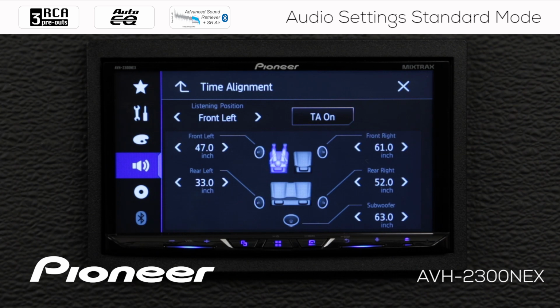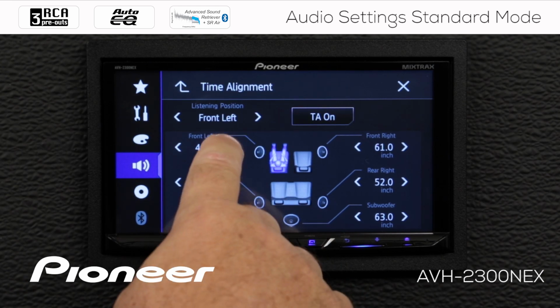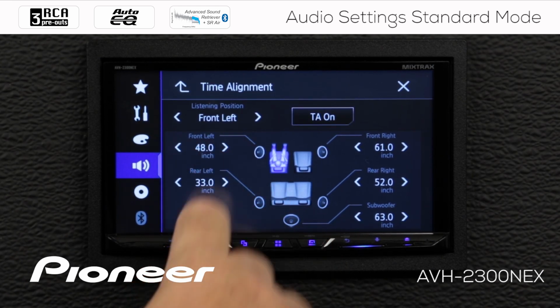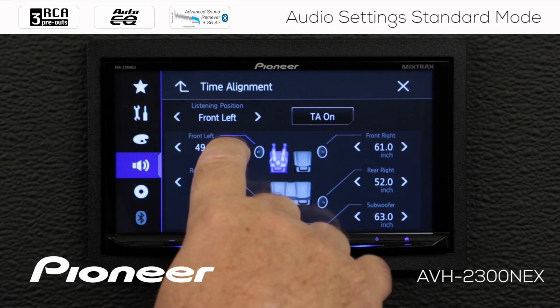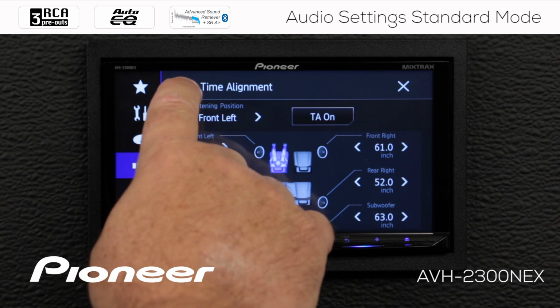Now, if you want to make those speakers appear to be a little further away or a little closer, you can make an adjustment by inch to the time alignment settings. And this will digitally delay or digitally move closer any speaker in the system. When you're done making your time alignment settings, we'll go back up.